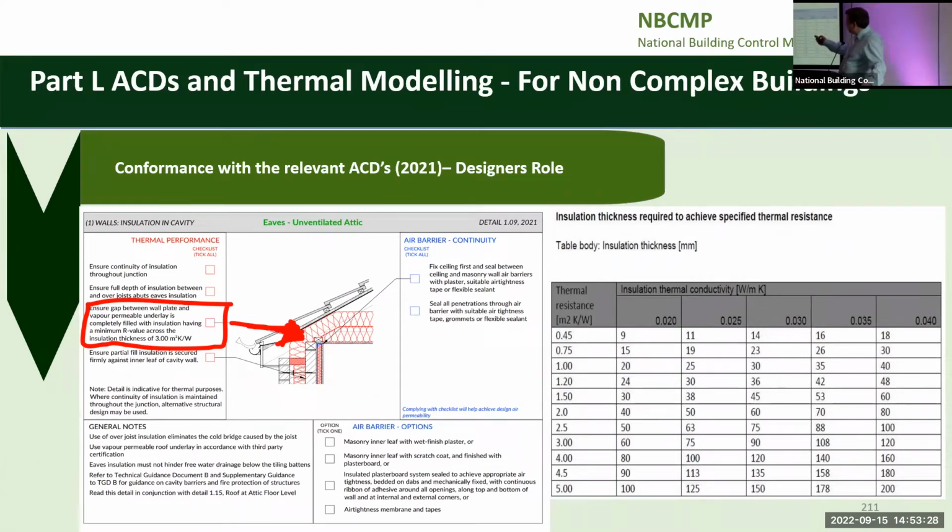Also, it's good practice to write your U values, the backstop U values that you're using, on your drawing, so that you can show that you have achieved your 20%. Maybe a note that could be done, in case they're revised again.